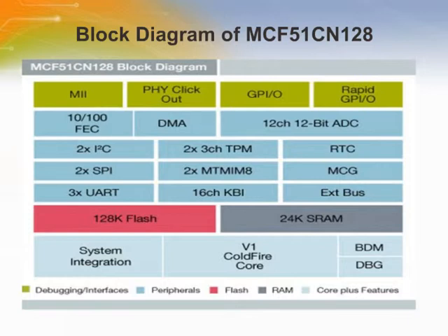It also has the TCP/IP communication suite, RTCS, with Telnet, FTP, and HTTP. Other features include 2 SPI interfaces with full duplex or single-wire bidirectional double buffer transmit and receive, and 2 8-bit resolution modulo timers with 8-bit prescaler, and up to 24 KB of static RAM, and up to 128K of flash.